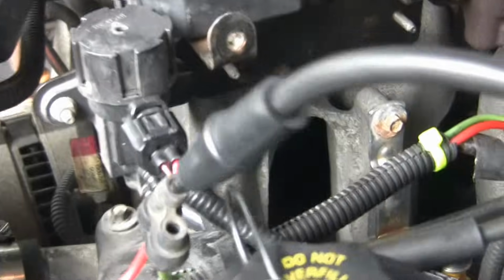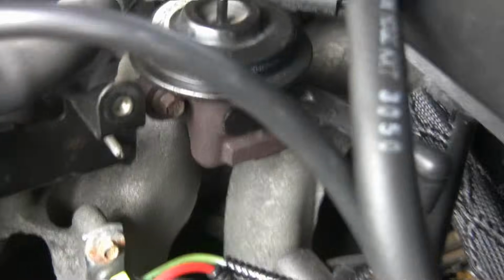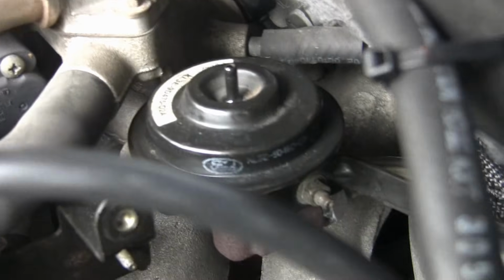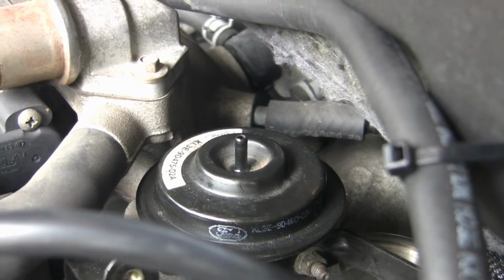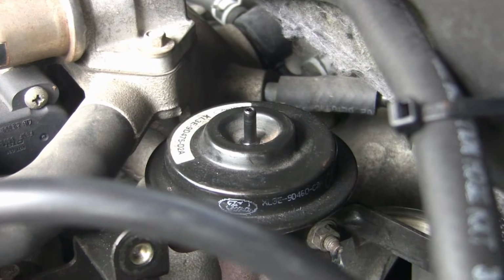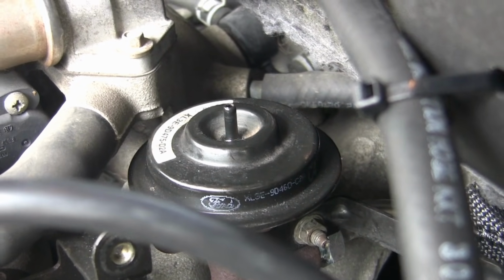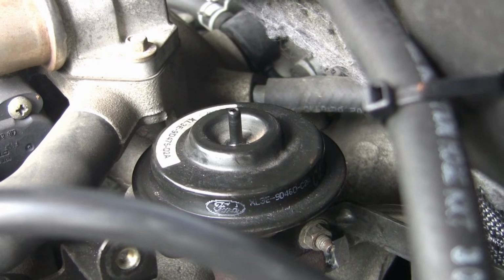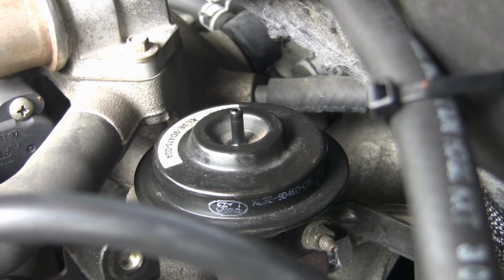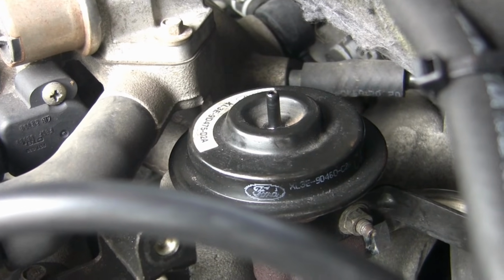Okay, well, as you can see, we had good vacuum. The engine shut off now, and when we applied the vacuum line to the top of that EGR, the engine did run a little bit rougher, but didn't come anywhere close to stalling. So that means there's a blockage somewhere, or possibly the EGR valve's not opening properly when it's got vacuum applied to it. So we'll take it from here, let you know how we make out.